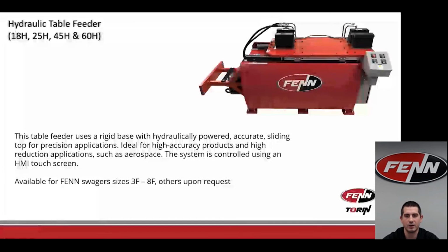So this one in this picture uses limit switches that your team sets up before your swaging application or whatever part you're swaging at that particular time. And then with a series of buttons, you can click run. You can jog the swager manually, jog the clamps, and then kind of create a program without a program, so to speak, using these buttons.